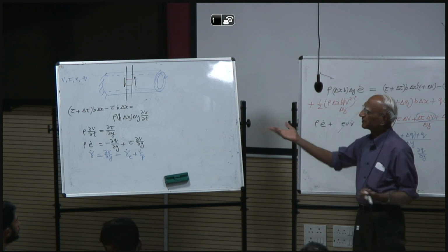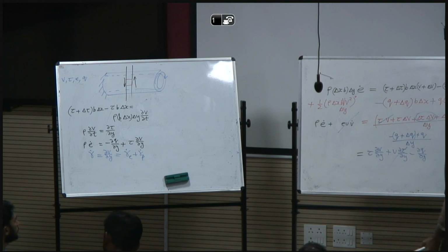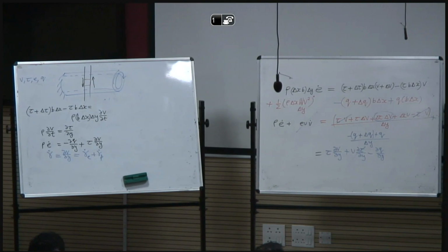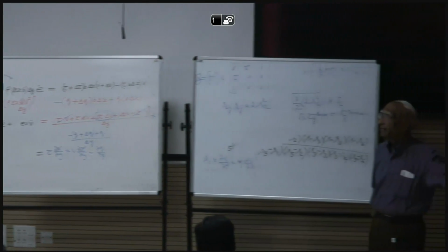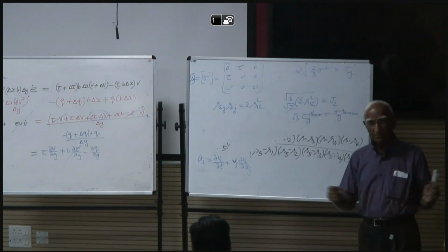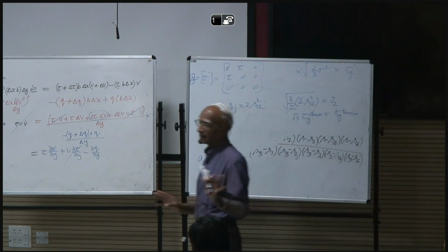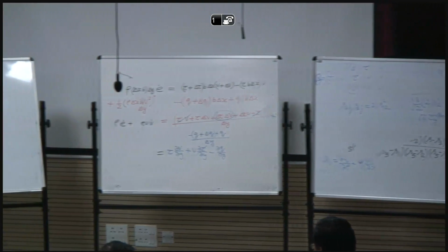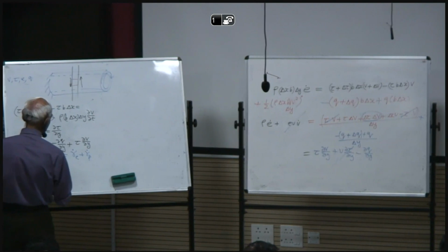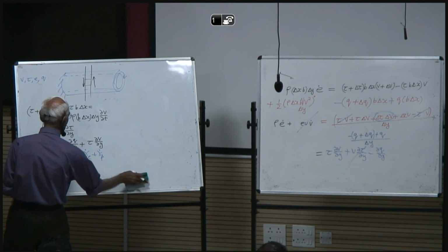In this case, the yield surface is basically tau y equal to some constant, if my yield surface is not expanding or shrinking. So I'm always supposed to stay on my yield surface. So the evolution of stress is only due to the elastic deformations. So I need a constitutive relation here. So my S dot is equal to twice mu of gamma E dot.